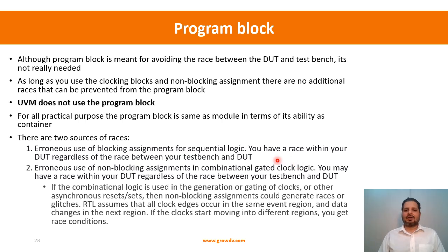So that is one fundamental reason. And the second fundamental reason for the races is the erroneous use of the non-blocking assignments in combinational gated clock logic. So if you create a gated clock logic for power savings, there are certain guidelines that need to be followed.